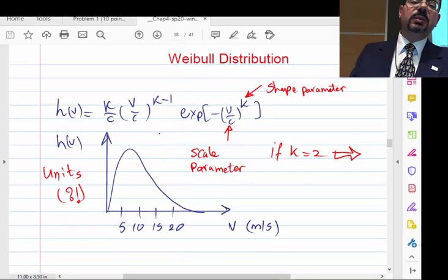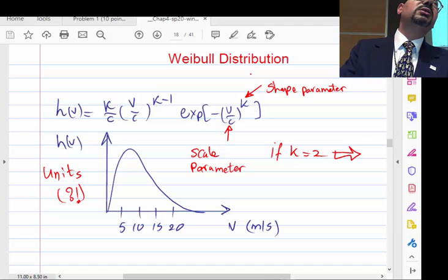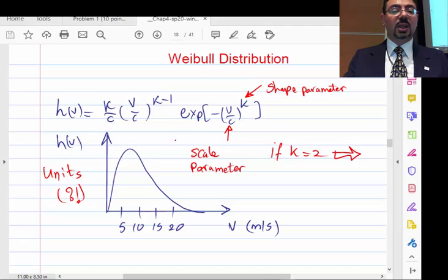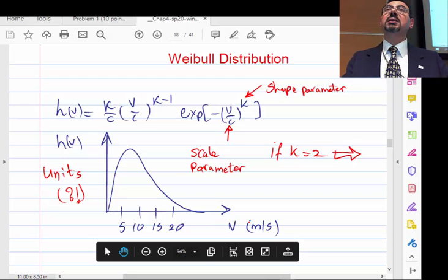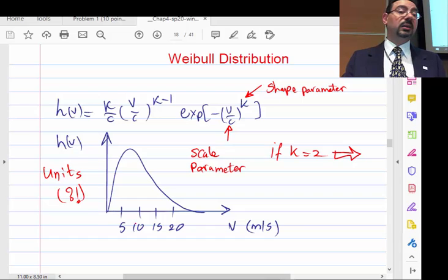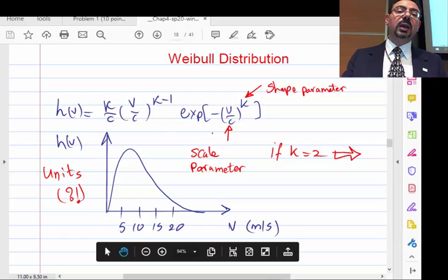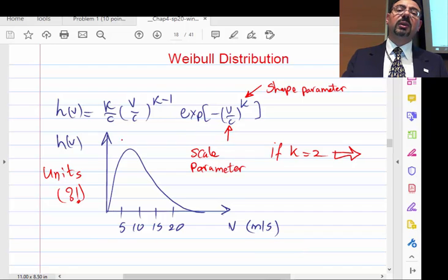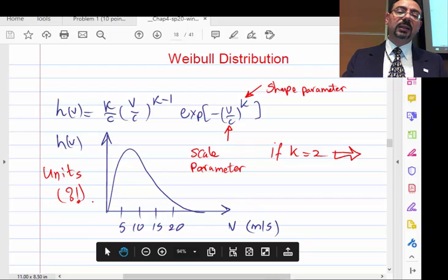They said that the Weibull distribution is really the way to describe the wind turbine statistics, where on the x-axis you have the velocity or the velocity bins, and on the y-axis you have either the hours or the percentage of the year where the wind stayed there. Okay, so it looks like Gaussian, but it's not exactly a Gaussian function, but it looks similar. But it allows you to have this long tail, and it allows you to have the shape of the curve depending on that K and the C.